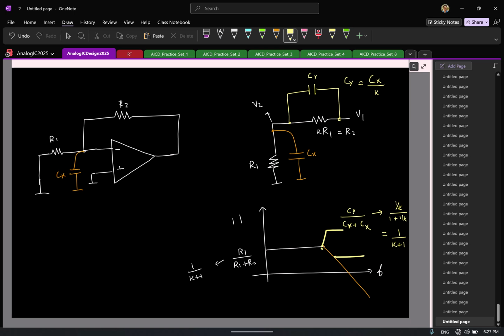So how will the transfer function look like in this case? Across frequencies, how will it look like? Yeah. So what's happening to the 0 now? Yeah, the 0 is exactly cancelling the pole, so that here you had the pole. There is no confusion, right? Somewhere. Now we introduce the 0. That 0 will now exactly sit on top of the pole and cancel it, so that you don't have any frequency variation. This is again another example of the unobservable or uncontrollable state, where you have the pole 0 cancellation happen.